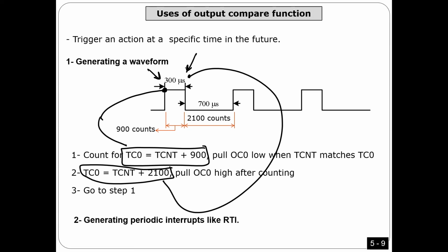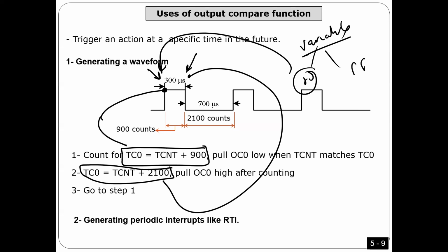How can you know? Very simple, similar to what we did in this course in several places, similar to the keypad, when we used the keypad. If you are in line 1, go to line 2. If you're in line 2, go to line 1. Same idea. So here I'm going to use a variable. This variable has two values, for example, 00 and FF. So 00 if it is here, FF if it is here, and so on, as you will see right now in the program. That's what I'm going to write inside the subroutine.